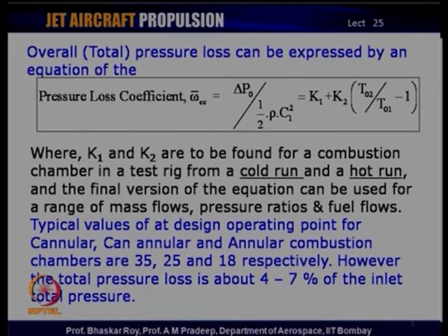So, once we get this equation partly from the rig testing and partly from the design parameters, we have a first cut handy equation to give us a reasonable idea about what the pressure losses are going to be across the combustion chamber. And this is, of course, to ensure that you do not lose a lot of pressure that has been developed through the compression process.